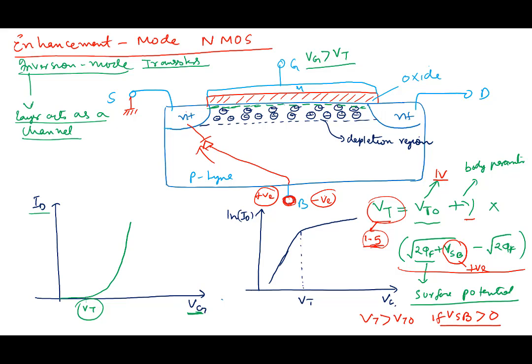So from this discussion we know that Vt is an important parameter. What does Vt represent? It marks the creation of a strong channel. Beyond Vt you get a reasonably strong channel here, and the current starts increasing, becomes significant with Vg. Below Vt the current falls exponentially. There's an exponential region here, okay? We will give you a model in a minute. So that's with respect to the gate voltage.